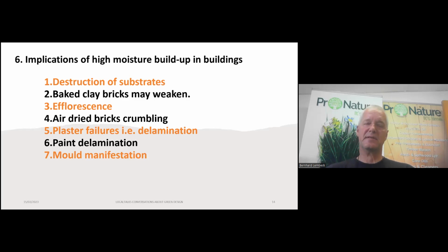We have this particularly here in Cape Town, in certain areas where we have a high groundwater table, and old buildings in part are showing bricks close to the foundations, where you can literally poke the brick with your finger. That's how soft they have become.